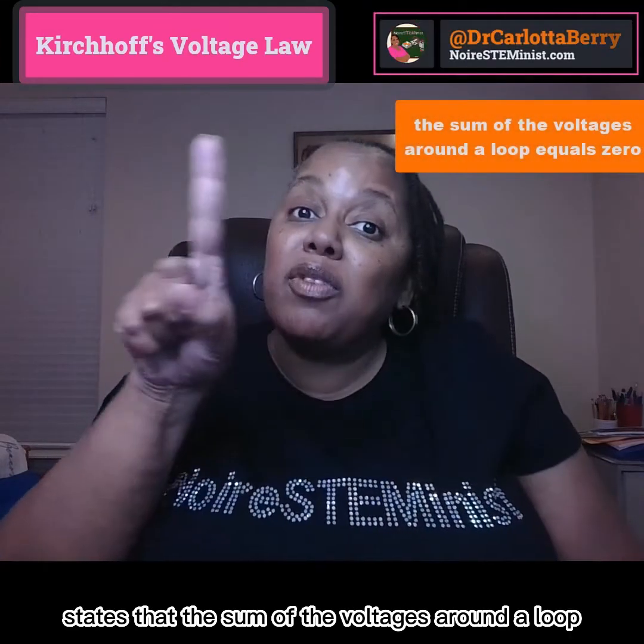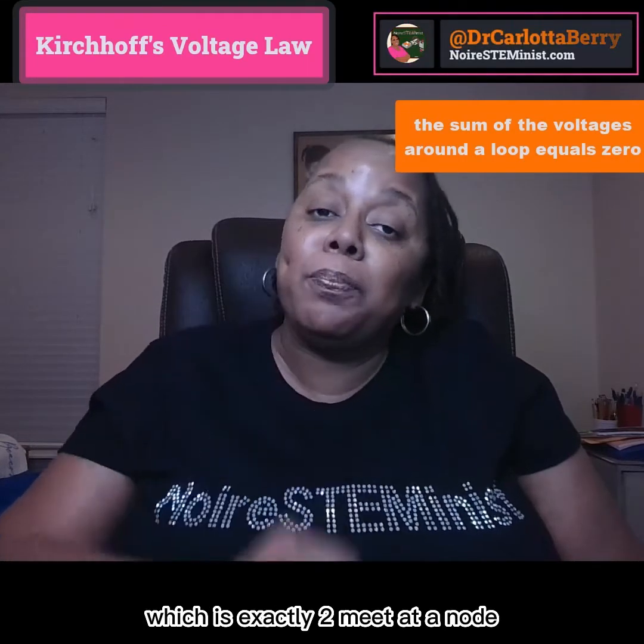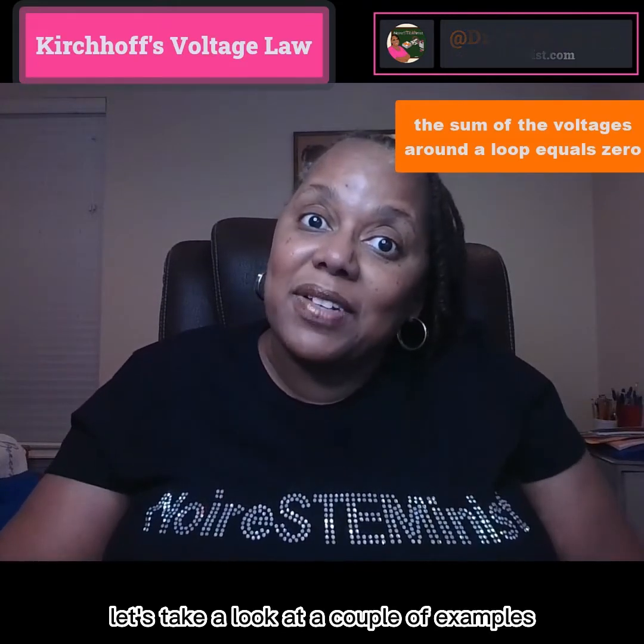Today we're going to learn about Kirchhoff's voltage law. Kirchhoff's voltage law states that the sum of the voltages around a loop is equal to zero. A loop of circuit elements, which is exactly two, meet at a node, and they share the same current, and it makes a big circle, thus the name loop. Let's take a look at a couple of examples.